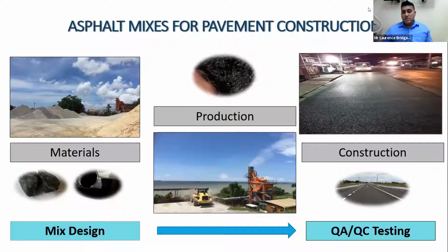In addition, these materials are required to be contaminant-free. For the manufacturing process, the plants are required to be inspected to ensure that batching, proportioning, and mixing at the required temperatures take place. As a result, controls within the manufacturing and the mix design processes go hand in hand.